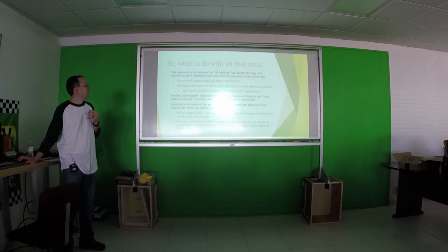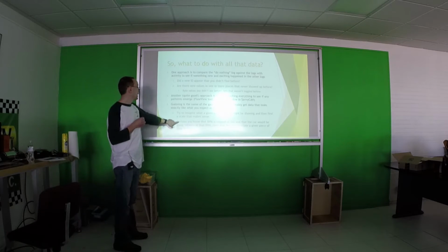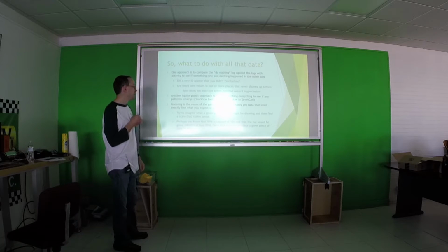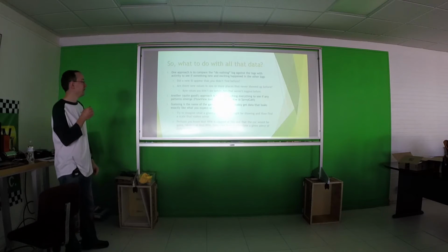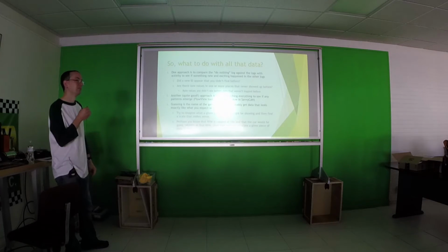Then once we get that data, we're trying to guess. Sometimes we'll see throttle data, or we're fairly sure it's RPM, but it might be scaled funny, say 10 to 1 and not 1 to 1. So sometimes we have to look at the scaling, but you can use educated guesses. If you know the RPM is capped at 16,000 and you asked somebody like Jack to floor it across the bridge, you can look for data and see when it hits 16,000. If it does, you know you found the RPMs and they're scaled 1 to 1, which I think on the Tesla it was. If they let you email files from jail.